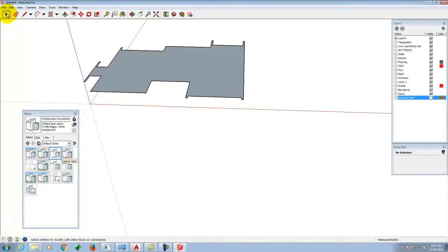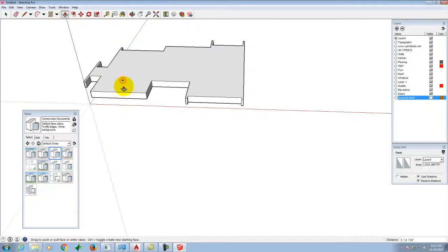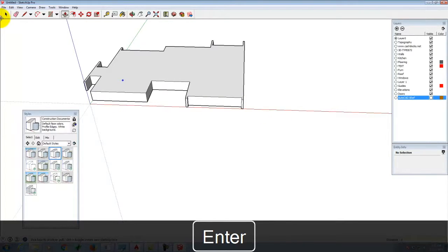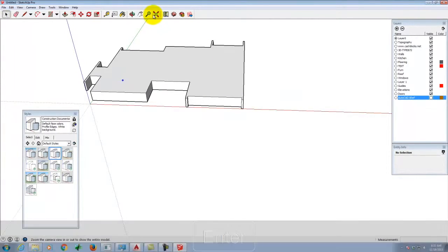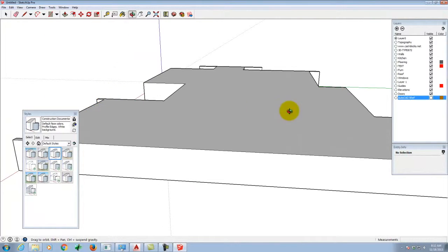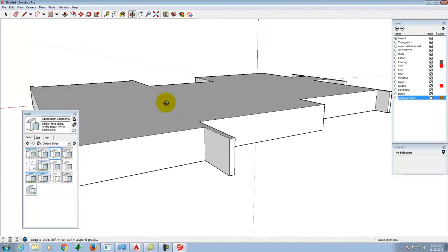Yeah, that one will work, just so that I can see the surface more easily. Okay? So this surface then represents kind of the foundation of my building. And I can go ahead and use the push-pull tool to move that surface down 3 feet, which makes then the overall foundation before I build up my walls. That makes sense so far?